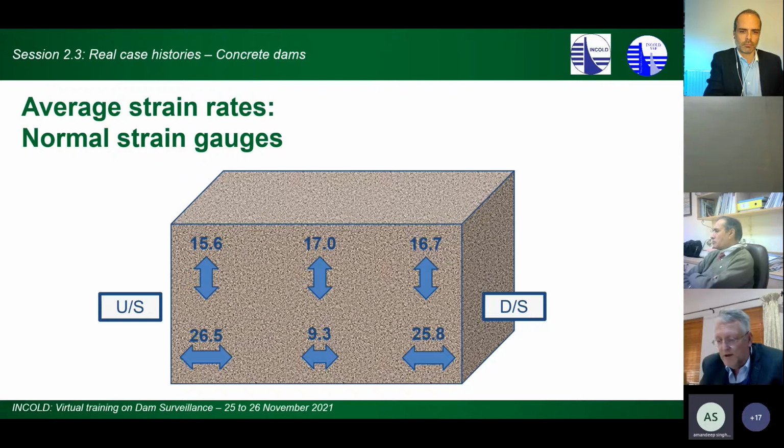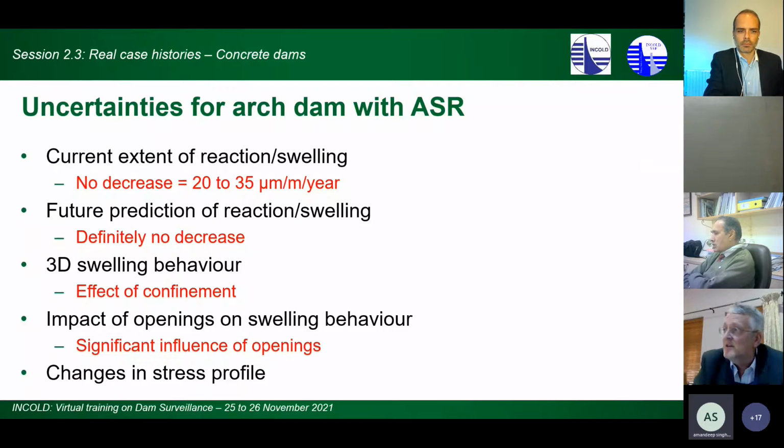And that's why you also get, it's proof why you always get cracking into foundations or openings where you actually have alkali aggregate reaction. So just if one basically concludes here, those are the extent of the swelling rates, unconstrained swelling rates.